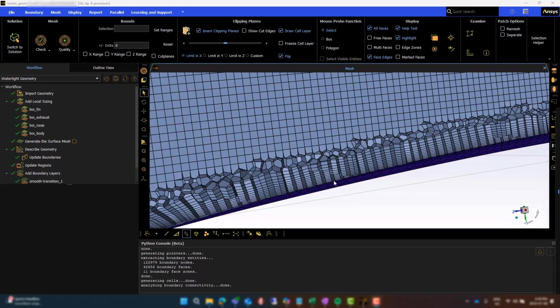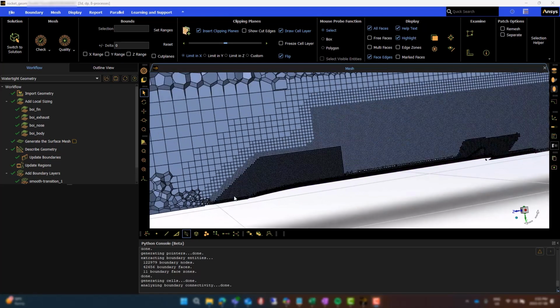For accurate modeling of drag and shockwave boundary layer interactions, a Y+ value of approximately 1 is required. Using the flow properties, you can calculate the first cell height required for a Y+ of 1 and assign that to the first cell height of the boundary layer. Or, an initial simulation can be run with the current mesh, and the geometry can then be refined and remeshed using this initial simulation's results.